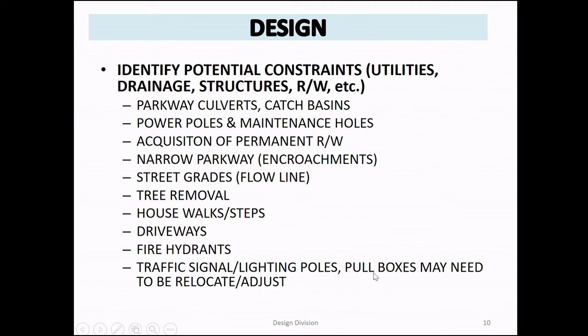Traffic signals, the most pull boxes, but most important is the push button. The push button has to be in a level area for someone using that curb ramp to be able to push the button.